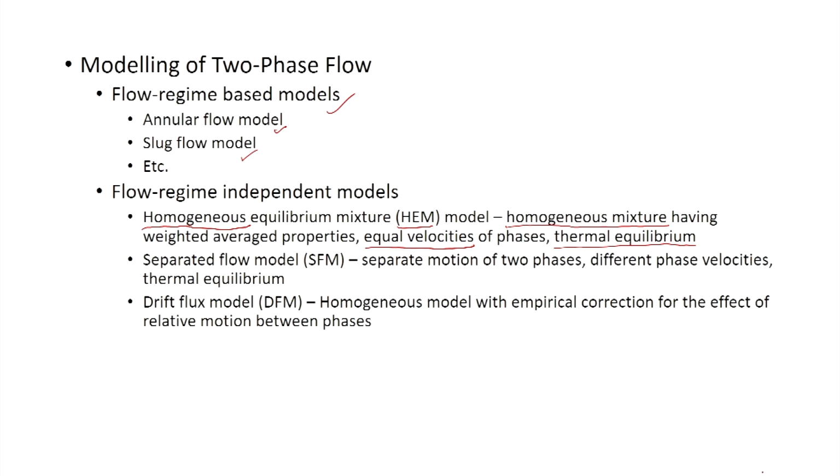Then there is a separated flow model, which is comparatively general. In this, the separate motion of the two phases is considered, and the balance equations for the two phases are written separately and solved. The phase velocities are taken as different, but thermal equilibrium is assumed.